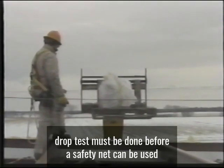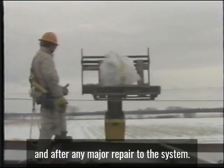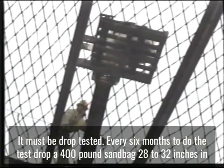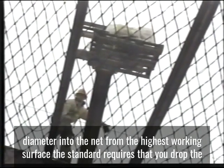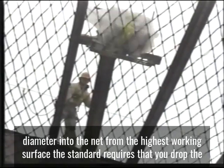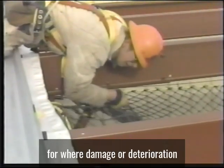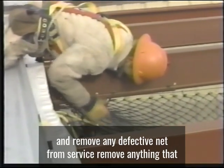Drop tests must be done before a safety net can be used and after any major repair to the system. If a safety net is left in one place for extended periods of time, it must be drop tested every 6 months. To do the test, drop a 400-pound sandbag 28 to 32 inches in diameter into the net from the highest working surface. The standard requires that you drop the sandbag from at least 42 inches above the working surface. Inspect safety nets each week for wear, damage, or deterioration, and remove any defective net from service.